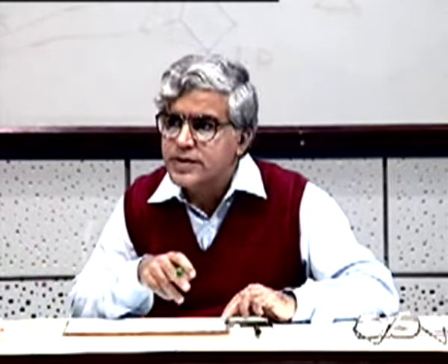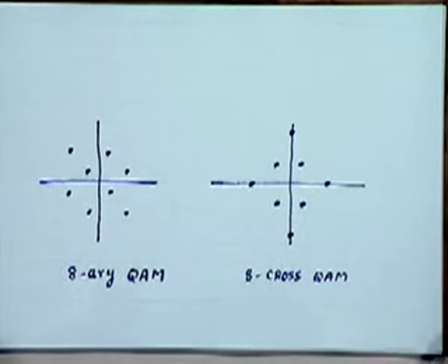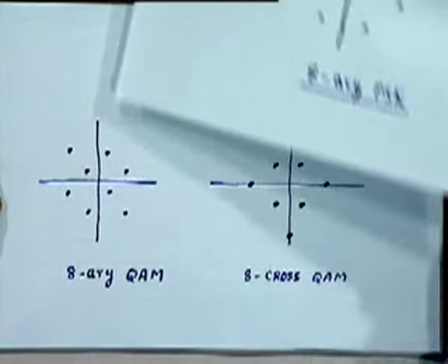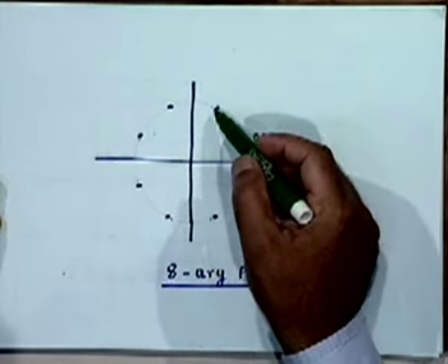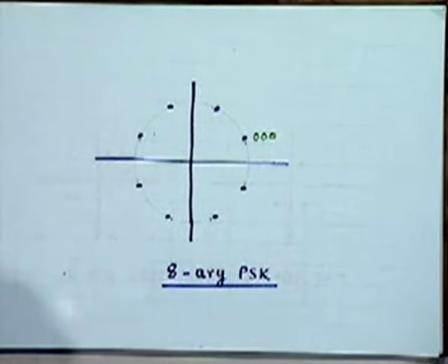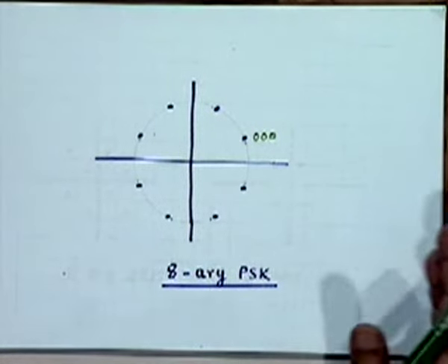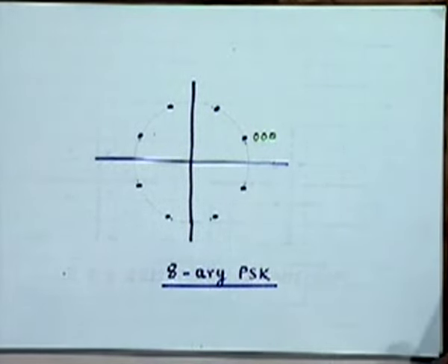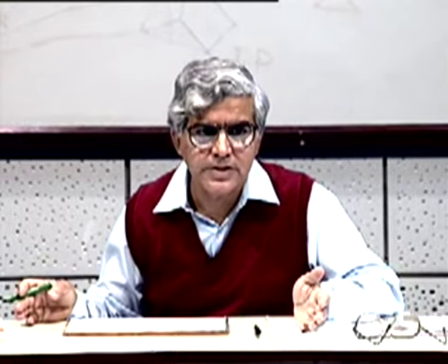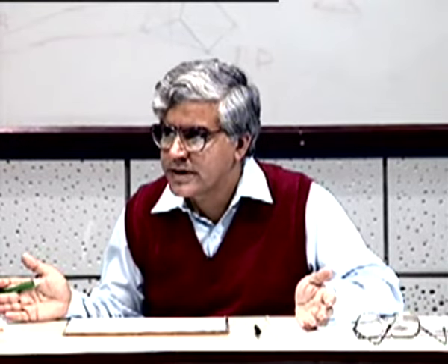How do these things all fall within the class of band limited modulations? Because it is understood or implied that each of these points will be using either a common pulse shape with the same bandwidth, or maybe at best we can use different pulse shapes all satisfying the Nyquist criterion or the required bandwidth constraint. Of course, usually one uses a common pulse shape.